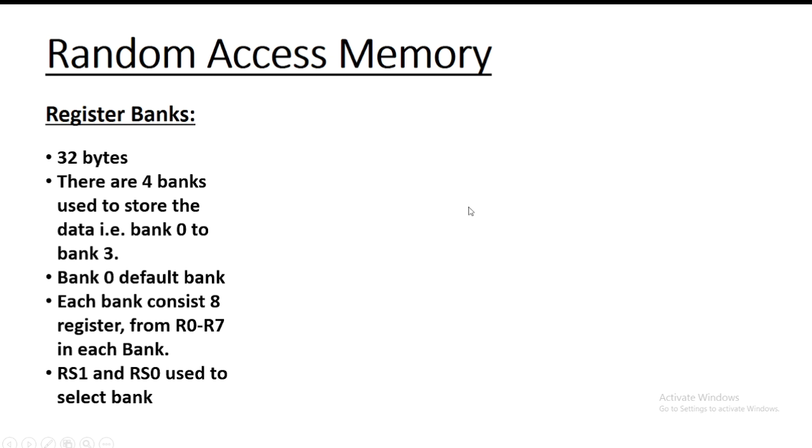The 8051 has 4 register banks, with each bank having 8 registers, which are used in many of its instructions, many of its arithmetic, logical, and other instructions. Those registers are numbered from 0 to 7, like R0, R1, R2, up to R7. These registers are usually used to assist in manipulating values and moving data from one memory location to another.